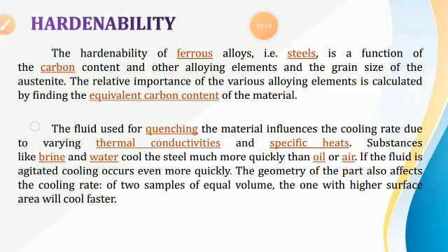I already explained the types of cooling medium: air, water, carbon solutions or brine. These are all media for quenching. Hardenability is also dependent on the quenching media, because the materials influence the cooling rate due to varying thermal conductivities and specific heat.